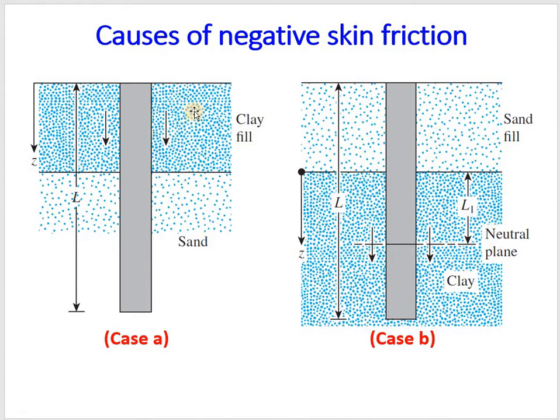Here, what is contributing to the downward drag is that this clay layer is consolidating, so that will lead to downward drag, and here also this clay layer is contributing to the negative skin friction. So these are the two cases which can be explained by sketches.